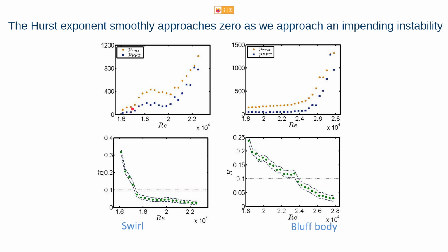The value slowly increases and it gradually increases towards high amplitude oscillations when your Reynolds number reaches 2.2 times 10 power 4 and up. Now you are not seeing any warning from the system because the system is gradually increasing, and there are situations where the RMS increases steadily and it smoothly moves to the higher amplitude oscillations.